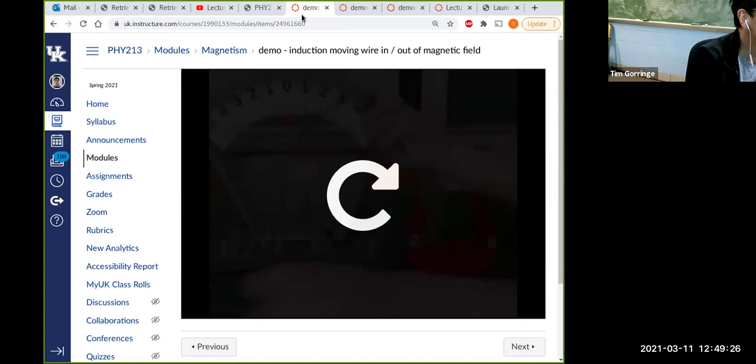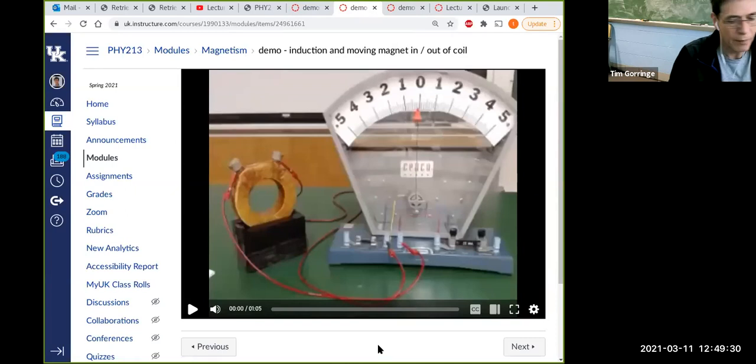I want to show you another one. Okay, this one is going to be even closer to what Faraday and Joseph did in those slides I just showed. So in this little video, I've got a loop of wire. Now, it's a little more complicated loop of wire. You see the terminals here of the wire on the left and on the right. And this is many, many turns of wire. So this is kind of like our version of Faraday's coil. There's hundreds, probably thousands of turns of wire in here. And its terminals are connected to this voltmeter. And I'm going to, like Faraday, like Henry, bring up a bar magnet to this many-turned loop of wire. So let's see what happens here.